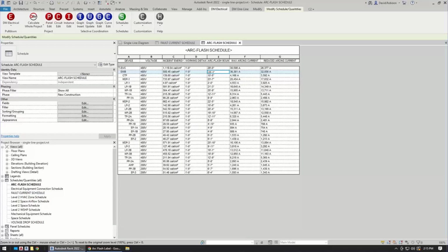There's a question, how do you address calculations through a transfer switch when supplied by a standby generator? That is a really good question, and our software does not handle that scenario very well. Essentially, to do that with our software, you have to disconnect the utility, so you have just the generator, and then run the calculation, and then reconnect it. It's not a great workflow, but you can do it that way. So you kind of have to manually make the connections to do the calculations.